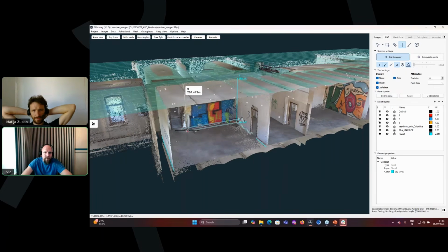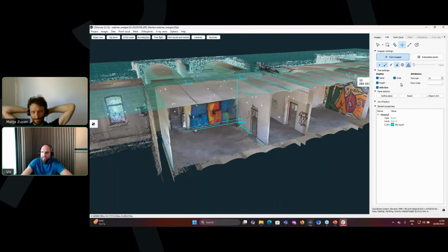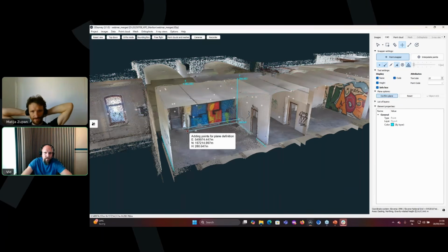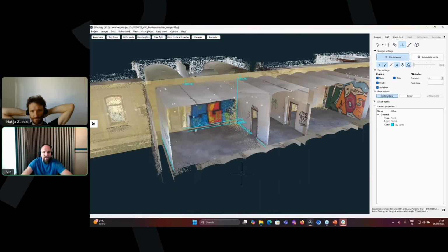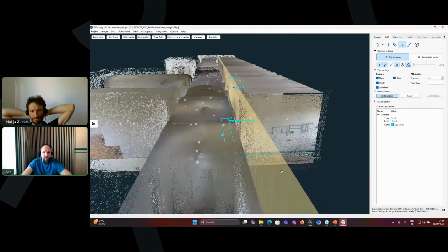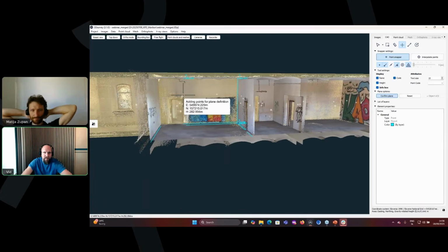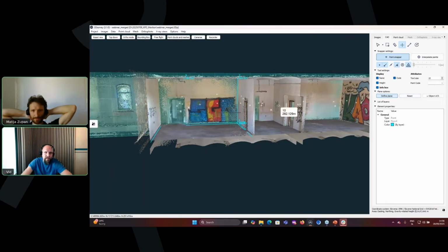Now I want to project this point vertically. I will go here and click on this endpoint like that. It creates a point up there. And now I will reset plane, define a new one, and I will select point here, point down there. Now it's still horizontal, and when I add the vertical, now we have the perfect vertical plane for this. And we can now confirm.